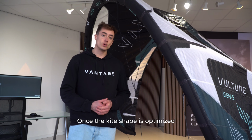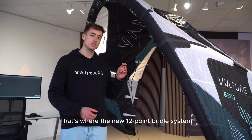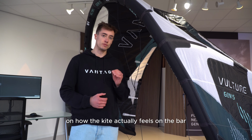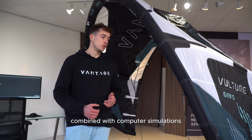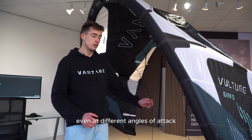Once the kite shape is optimized for maximum performance, those forces still need to reach the rider. And that's where the new 12-point bridle system of the Gen 5 comes into play. The bridle configuration has a huge influence on how the kite actually feels on the bar. We tune this bridle system with underwater validation in combination with computer simulations to showcase how the forces are distributed along the bridle, also along different angles of attack.